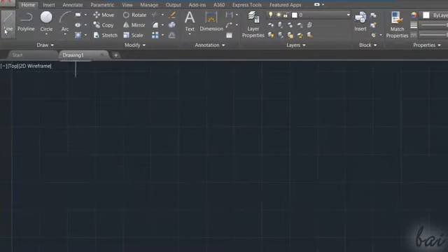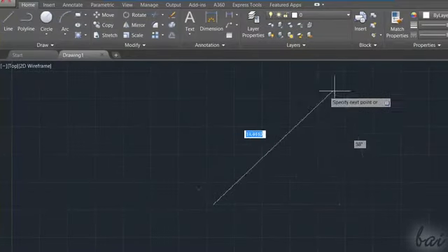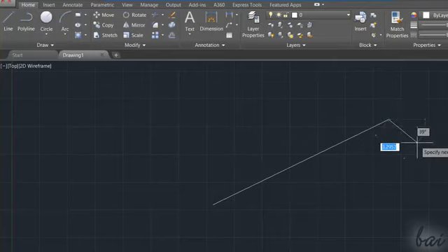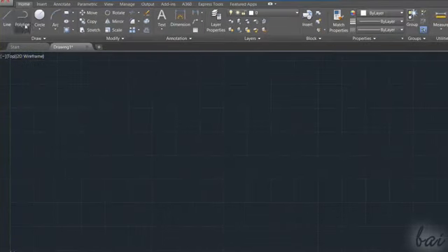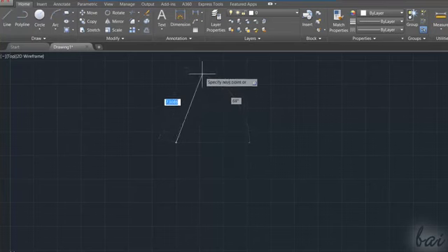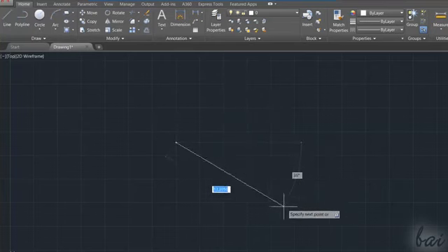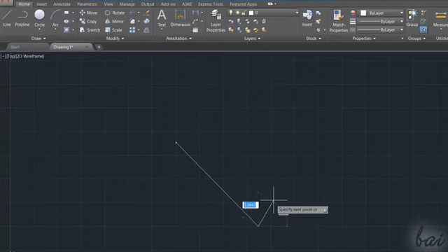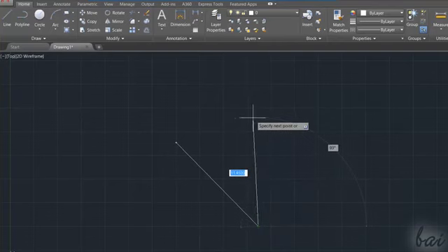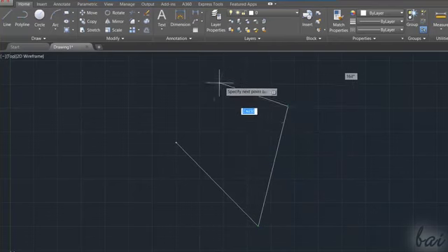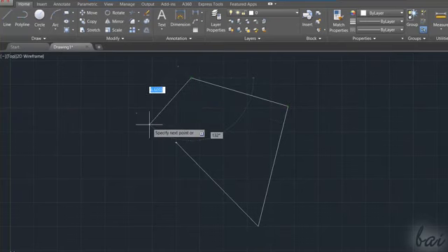Use the Line or the Polyline tool to draw basic lines and segments. On the empty space, click once to fix the first point, and click once again to fix another point in order to place the first segment. So, you can go on clicking on the workspace to place other segments sharing the last fixed node. Use the Escape key to stop drawing.